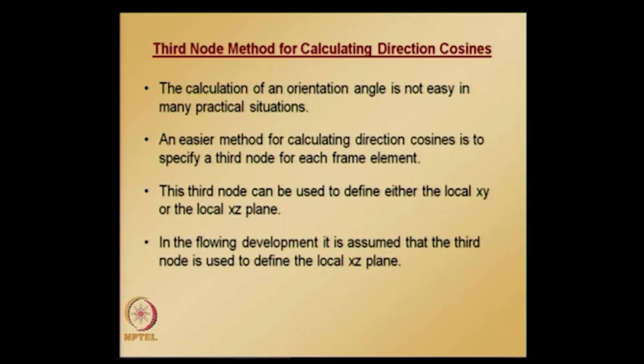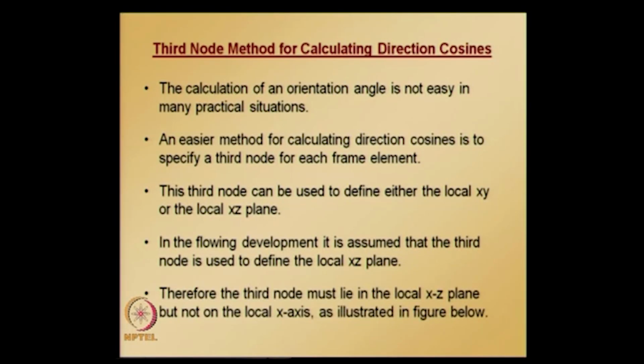And in the following development, where we are going to derive equations, it is assumed that the third node is used to define the local xz plane, and therefore the third node must lie in the local xz plane, but not along the local x axis. This is going to be clearer to you when you look at the figure.